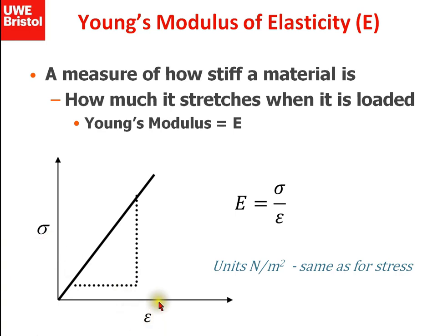And where you see strain, imagine you're seeing elongation there. And remember that stress is the way to look at force, getting rid of the effects of geometry, so we're doing force divided by area. Strain is a way to look at elongation, again getting rid of the effects of geometry.